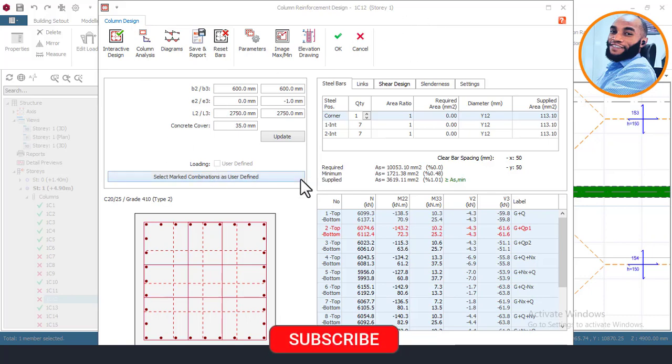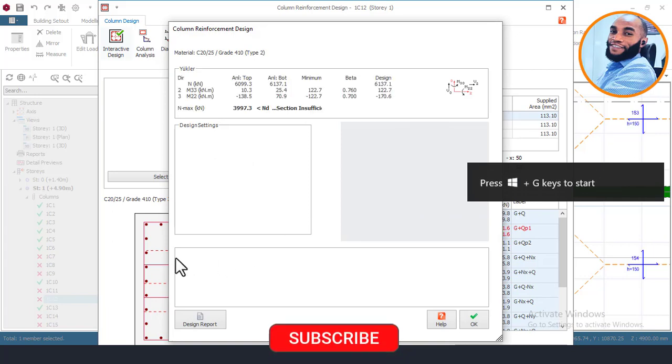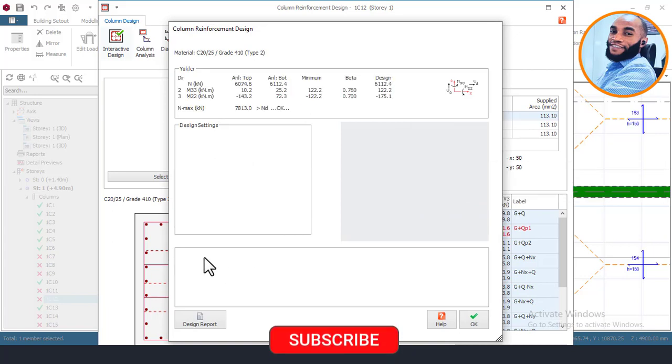Here, the first thing we'll do is check the reason why the column is failing, as I said in part 15 earlier. Right now, I'll click on interactive design here. Once I do that, there will be a warning around this place to show the reason why the column is failing. So let's see the reason.